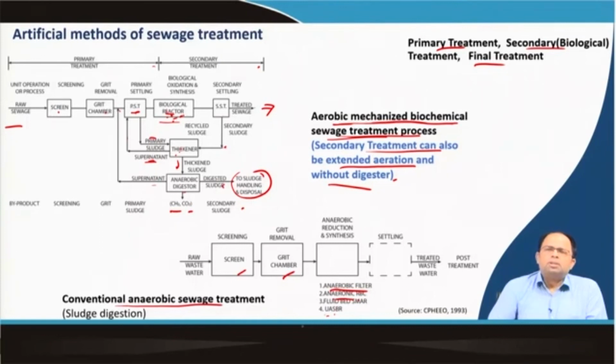So, there are several processes that could be involved where we can get rid of the settling tank, depending on how much digestion takes place, and then we have this final settling tank where both the suspended solids as well as the excess sludge from the organic matter could be separated. It depends on how we organize this particular system, and what kind of treatment we devise.